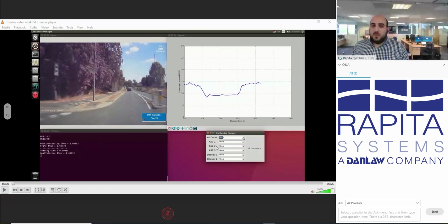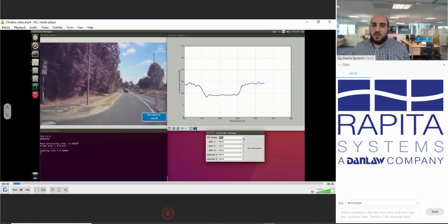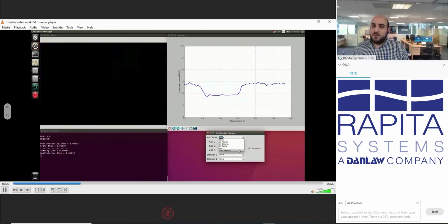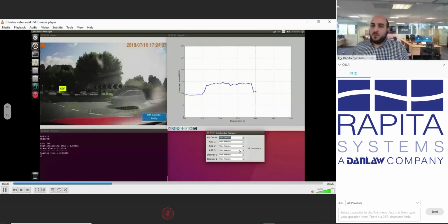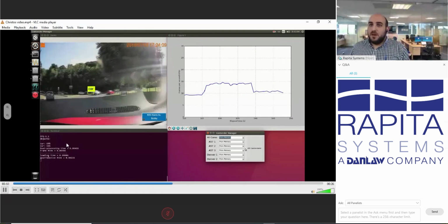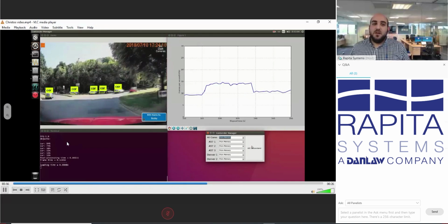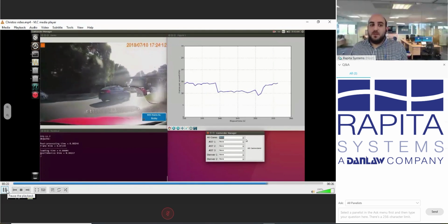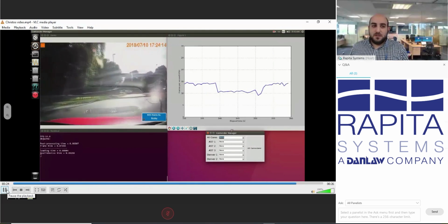And we can use the simple user interface, which is also on the screen, to select what kind of contention we would like to add to the system to see the impact. So in this case, we select main memory as our source of contention, and we can see that the frame rate drops from 15 to just above 10 frames per second. So we can see that there is indeed an impact, and that impact has to be analyzed.